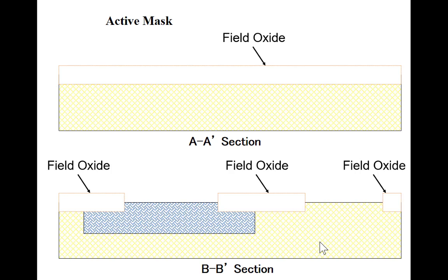So what we do is we put the insulator on, so our conductors are way above the surface, so that the capacitance between the gate and the silicon is so low that we don't get enough force to create the inversion layer. So the field oxide then provides isolation between devices. It provides isolation by essentially raising the threshold voltage up to a very high level. Make sense?